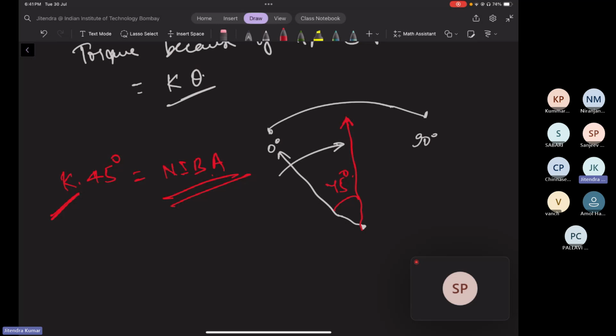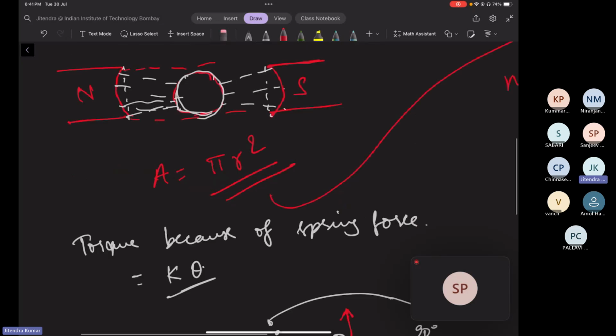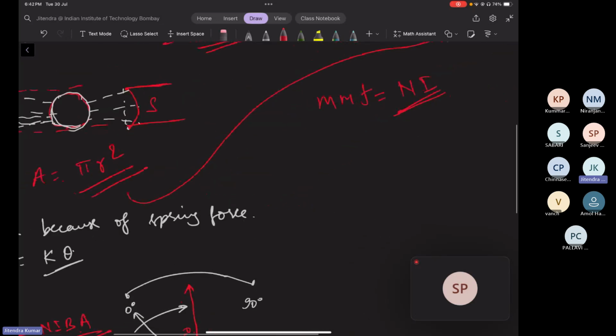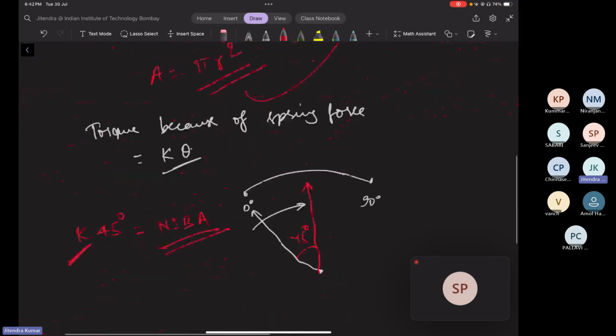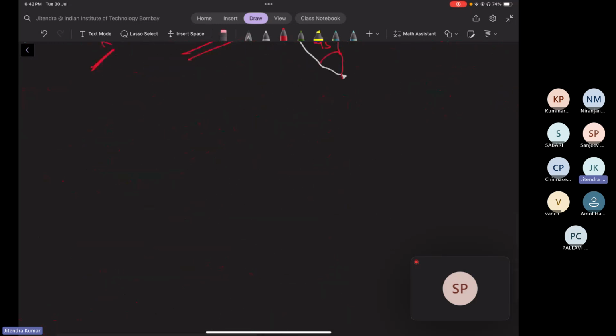So that is how we generally calculate. In a galvanometer, we generally see this PMMC type of instrument. In a galvanometer, we consider T equal to K i, where K is nothing but B A N into i. So this is your galvanometer constant G i. We will solve one question based on that.